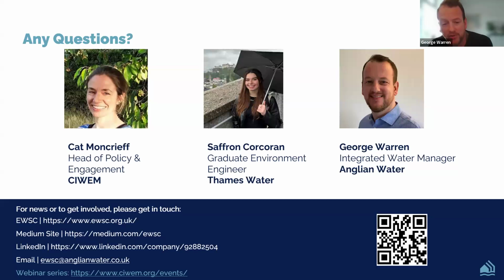But I believe that will be addressed over the next 12 to 18 months. In terms of should we be mandating dual supply, I think there's a good case for it, if I'm honest. One of the things that we spoke about in the previous webinar around costings is that the additional cost of incorporating the internal pipework is around £350 additional cost per property. Now, the £350 to future-proof a building so that you can plug in a non-potable supply when it's available. Now that I believe is worth doing.